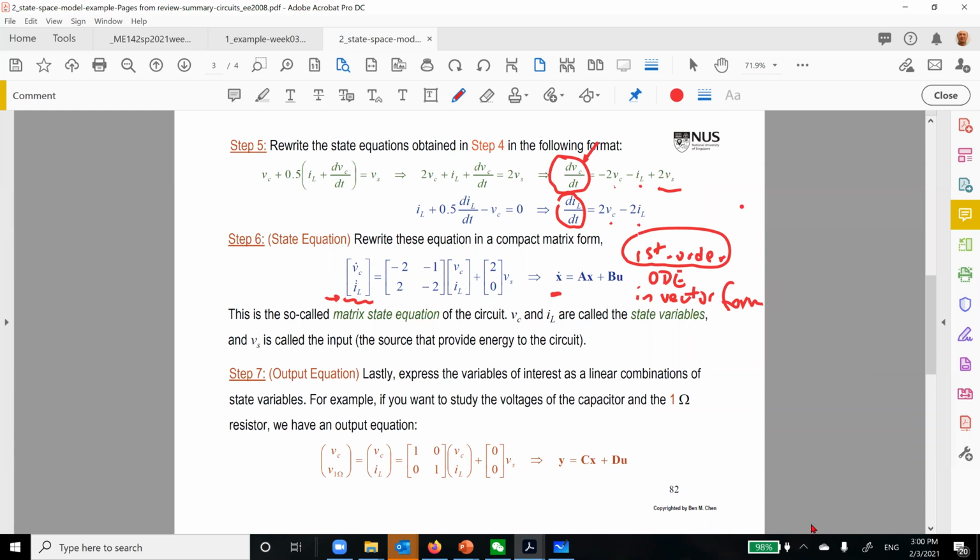So it's the voltage along there. I may have two things I care about. Instead of just the voltage across the capacitor, I care about this. But also I care about this load, 1 ohm. The 1 ohm is the current times 1, so the current times 1 is IL. IL is my state variable.